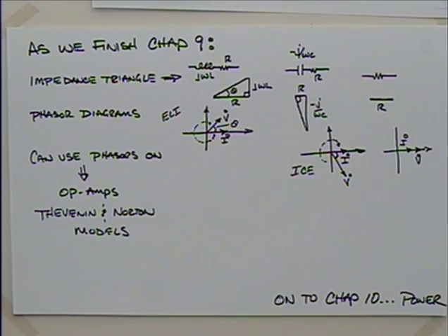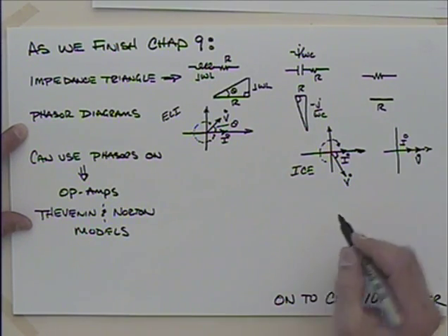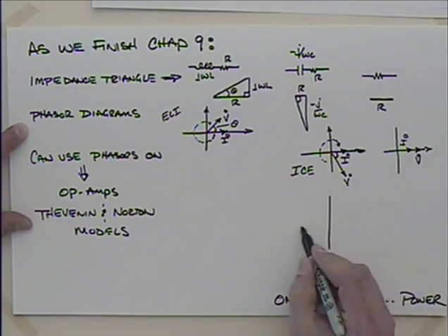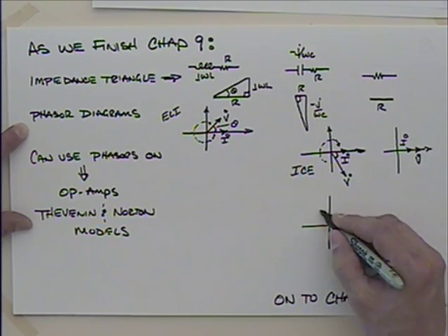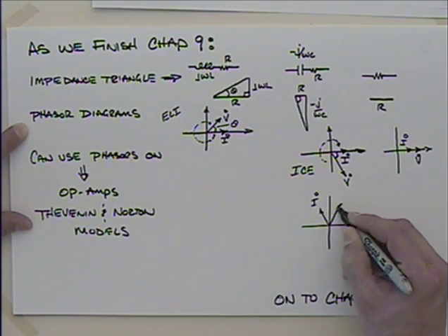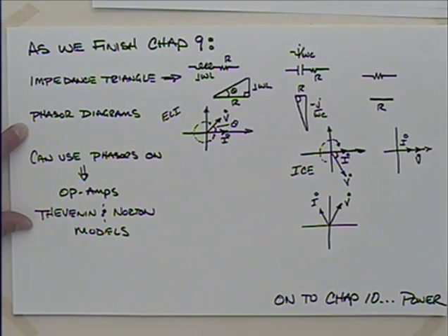So with that graph right there, with V, the voltage, it's in the fourth quadrant. Okay. So we have to start not at the positive x-axis, but from the first. The location doesn't matter. It's the relative position. So let me come down here and rotate this thing a little bit. What if I come up with I like this and V like that? What's leading? I. It's exactly the same capacitor.